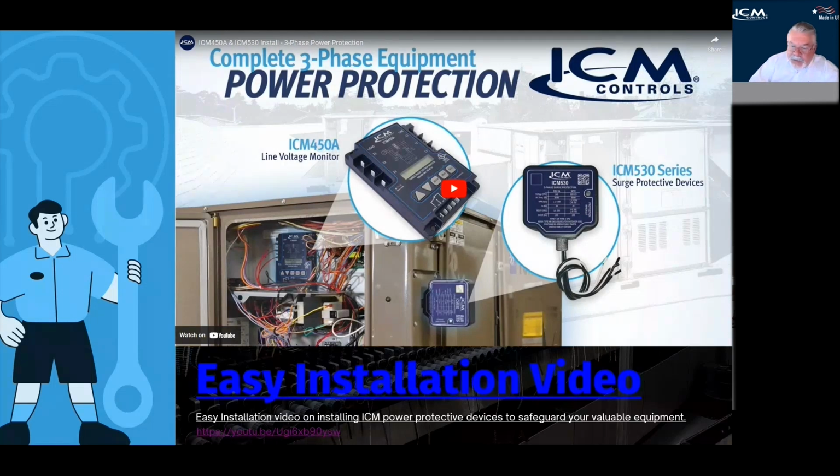The thing is, a surge is a different kind of animal. A surge is a very rapid event, and a line monitor won't always see that. It happens too quickly and can actually damage the line monitor itself. It can damage the equipment. Still, a line monitor is not a surge protector. A surge protector is not a line monitor.